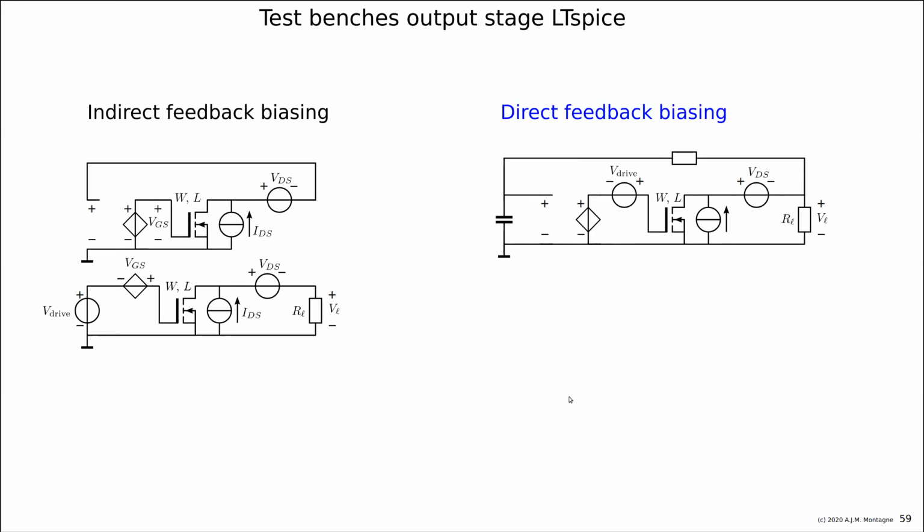And we have seen other means, because here we are really making a drive voltage and we can put any shape of the drive voltage there. But basically what we are interested in is just the design of the FET. We just want to know what is IDS and VDS and what should be W and L of the FET. So that's the only question to be answered. So a simple DC sweep with a biased FET would also be okay.